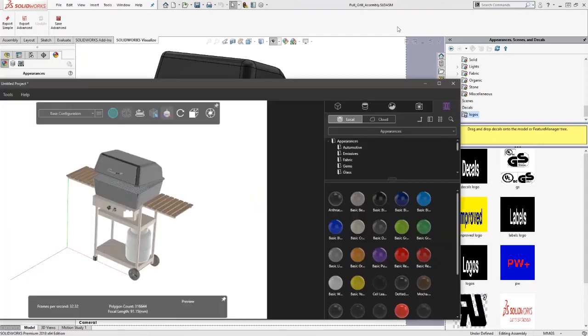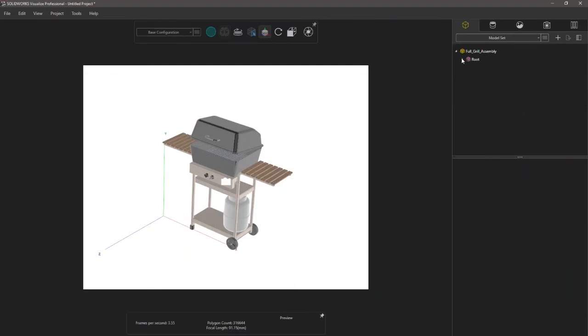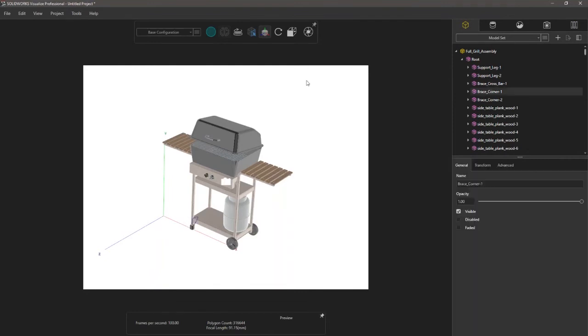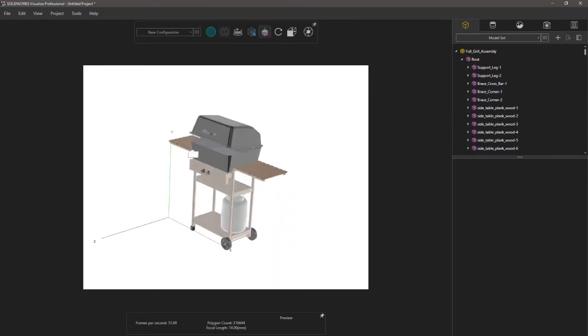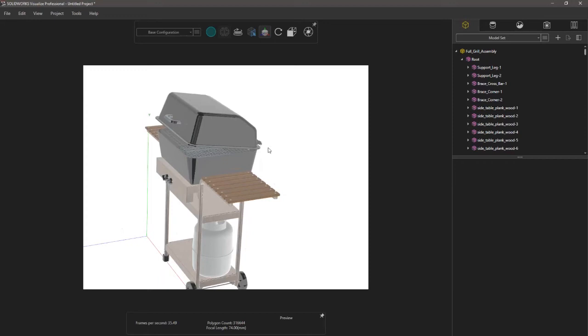And then if we look at my assembly tree here, if I expand it out, I should have the root folder, and now instead of everything having an appearance name, it actually has the file name, right? So I have individual parts I can select, and this is useful if I do need to accomplish motion. Now, I would always recommend, since SOLIDWORKS has mates set up, if your mates are already set up for the motion, it's easier to just pose the model in SOLIDWORKS and then export it.